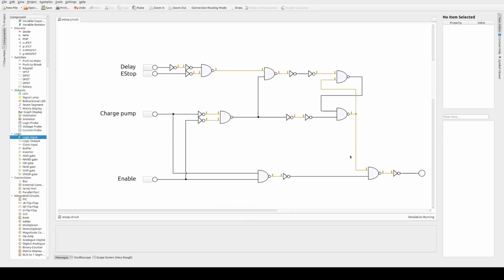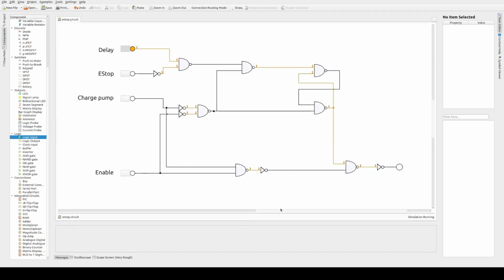But if we add in the rest of the circuit and convert all of the gates to equivalent NOT AND and NOT gates, we get quite a lot of double inversions, and these just cancel out. Now we have 7 NOT AND gates, which will be 2 quad NAND ICs with 1 spare gate, and 5 NOT gates. We could convert any of those gates to single NAND gates too, but I'm going to hold on doing that until I've integrated it with the rest of the circuit, because we have that one Schmitt-Trigger inverter IC for the charge pump detector already, and we know we can spare some of the gates on that.